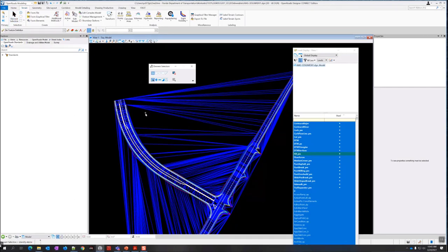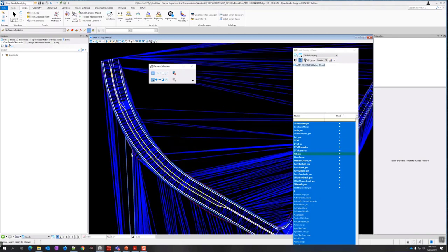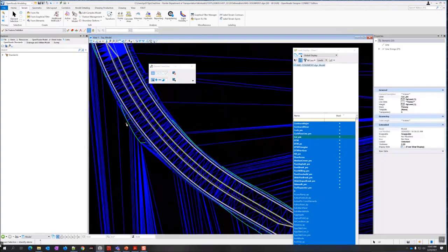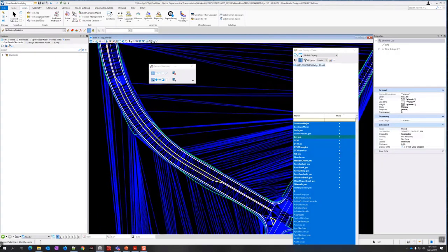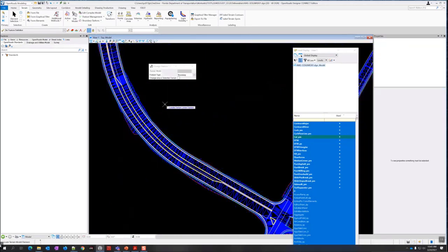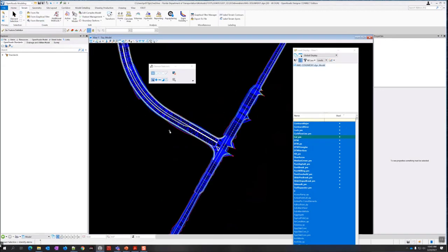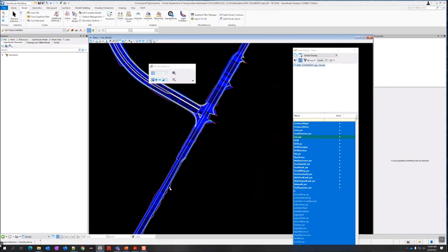and I'm going to do select all on level by element. This time I'm going to do the cut. So I did the fill already, and I'm going to do the same command under feature management. So I'm just going to click that button, go back to the last used command, data point to change 22 selected elements. There we go. So the first one, you may not see much of a difference. You have to apply them both. So that cuts out most of the triangles by making those cut and fill PMs a boundary.